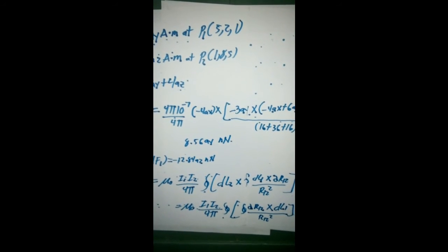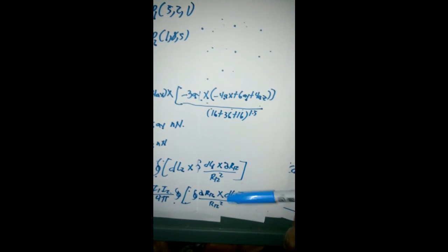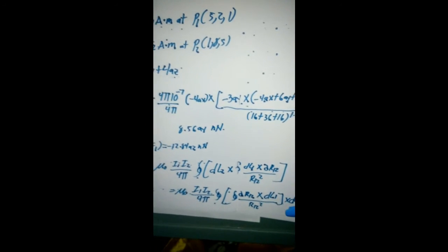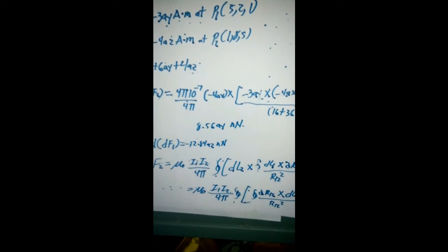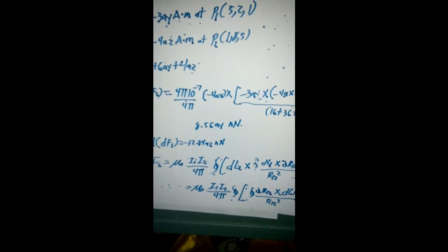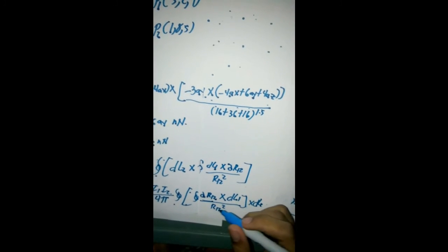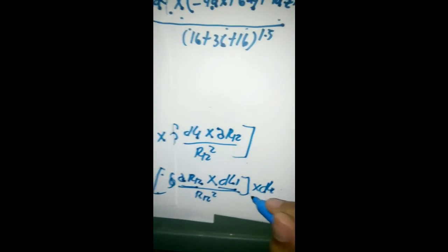Although we shall only give the result, it is not very difficult to make use of this equation to find the force of repulsion between two infinitely long, straight, parallel, filamentary conductors with separation d, and carrying equal but opposite current I. The integrations are simple, and most errors are made in determining suitable expressions for aR12, dL1, and dL2.